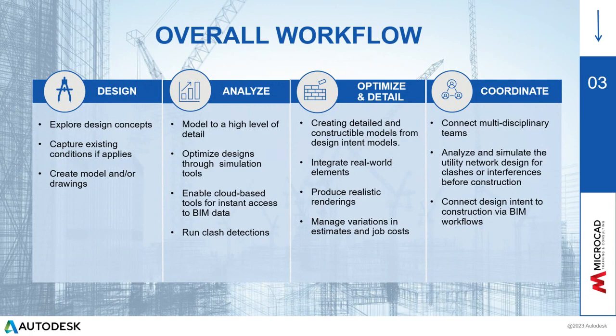So the first step in this workflow is the design. Everything starts from an idea. Once that idea is conceived, it is time to create a model or drawing that reflects what we want to transmit for generating the schematic design. If the job will be done in an existing area, the existing conditions must be considered, but not with documentation. Normally, existing conditions are plans, PDFs, or just printed plans. The best solution with the AEC collection here is a reality capture with a scan done with ReCap Pro.